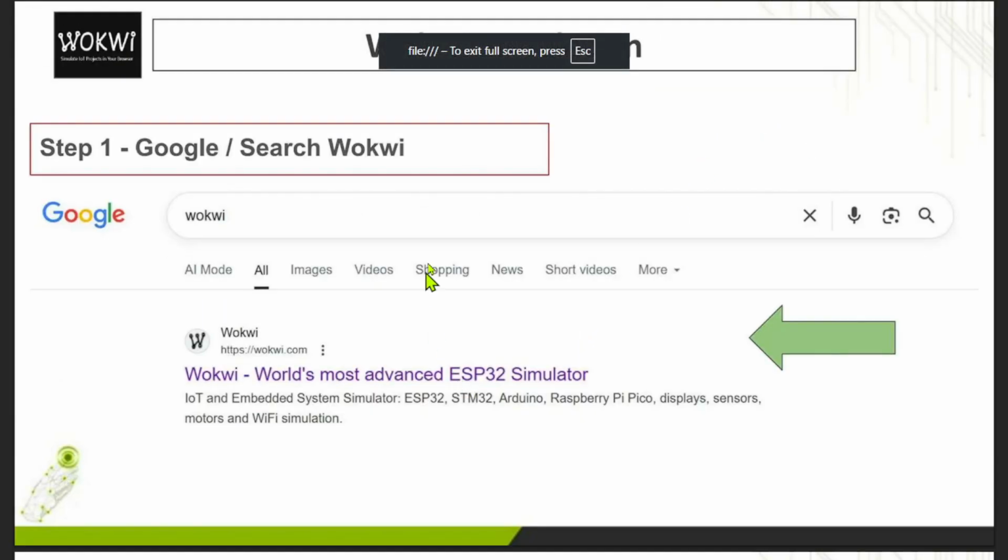so before going to develop our project, let's see about the ThingSpeak platform. Okay, so how to do an IoT project? As we saw yesterday, we are going to use our Wokwi platform, because this platform consists of ESP32, and ESP32 has Wi-Fi. That Wi-Fi will connect all the data to the internet, that is, the cloud. So we are going to upload all the data into our cloud, and then we are going to see the output in our web dashboard from anywhere in the world. That's the really important part of IoT.